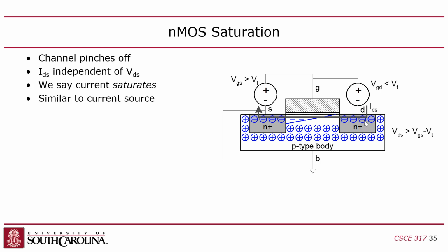And this is called the saturation mode, where the voltage difference between the source and drain is so high that it causes the difference between the gate and one side of the channel to get pinched off. Then the transistor will stop giving you more current as you increase the voltage. So it goes out of linear mode and into saturation mode, and the transistor becomes a constant current source at that point. You guys with me?